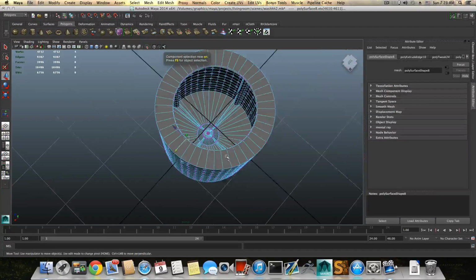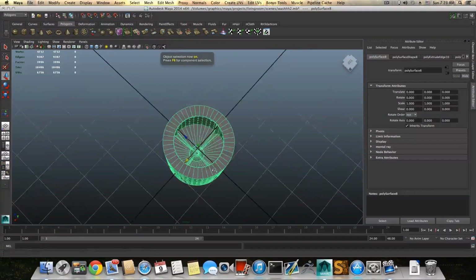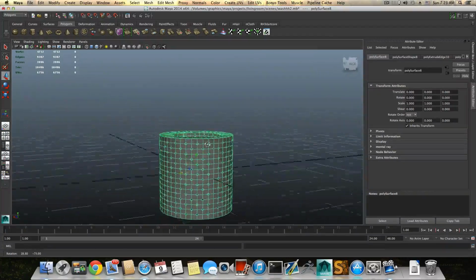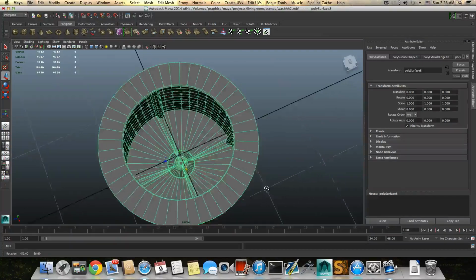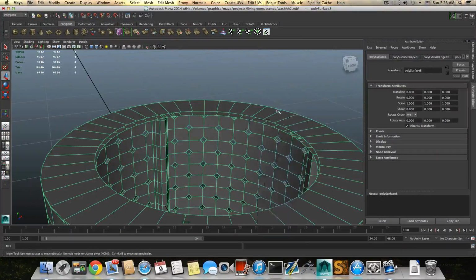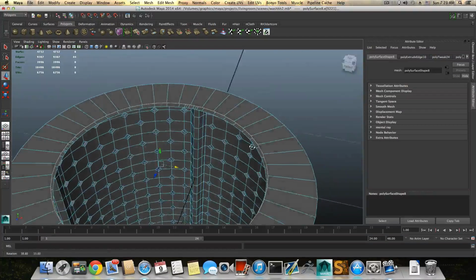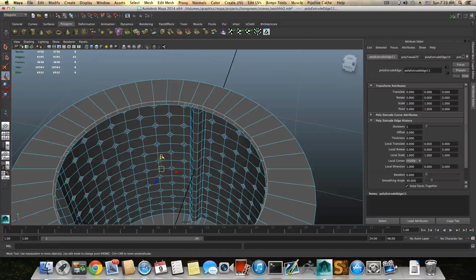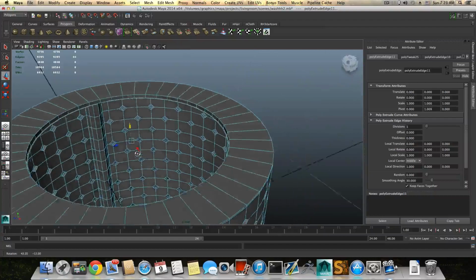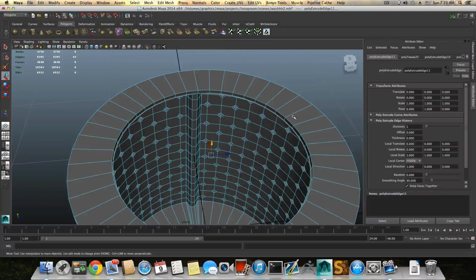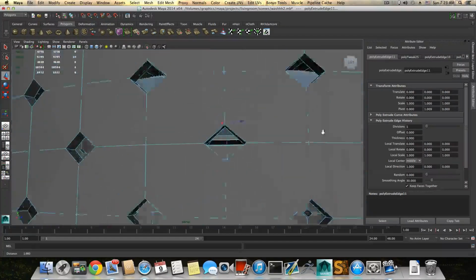Press F8 and bring it back to object mode. So it's basically done, okay, there is nothing more to it. I will leave this area open, or you can simply grab this and extrude it and just bring this down that way, but pay attention that there is not the same number of vertices in those faces and the lower faces.